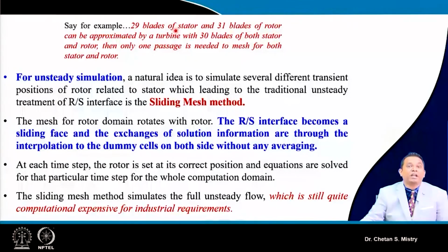Now the next approach is unsteady simulation. For unsteady simulation, mainly what we are looking for is the exchange of data between rotor and stator, which happens with the sliding mesh approach. Under that configuration, whatever data we analyze at the exit of the rotor domain, using dummy cells, all calculations are done.